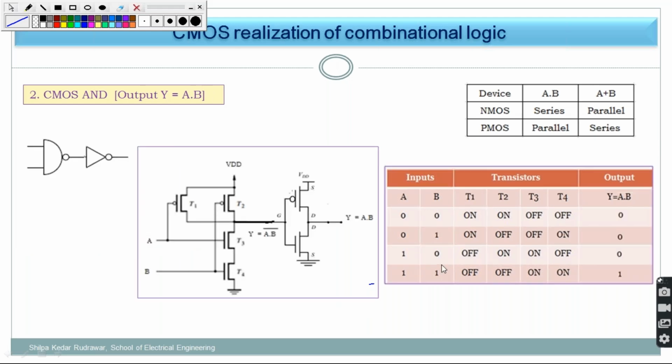So here, this is the circuit. Are you able to see? So here we have implemented AND logic. So how to implement AND logic? The NAND logic, which you implement directly using CMOS, and in front of that you put one NOT gate, this is the NOT gate. Proper notations you need to give. As I told you, this is the source, drain, gate, again drain, source, likewise every time you need to give notation. So what will be the difference in this truth table?